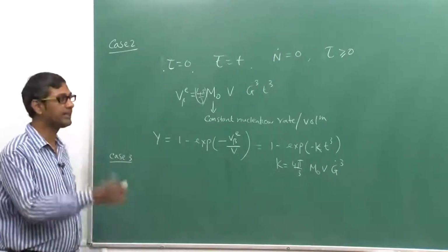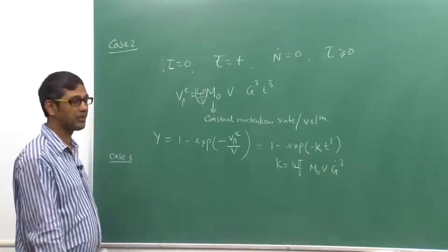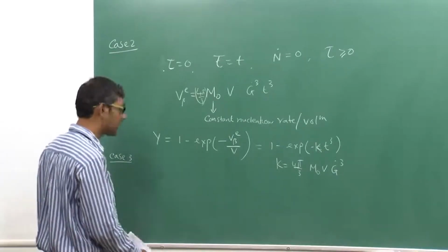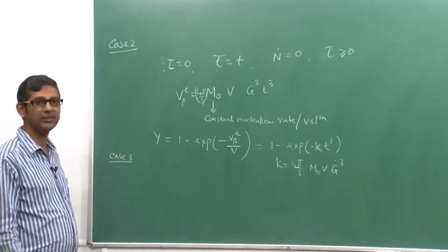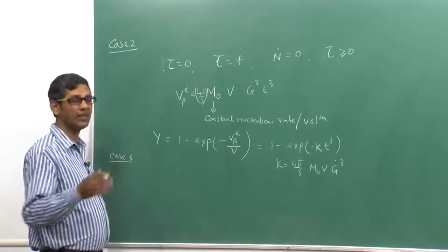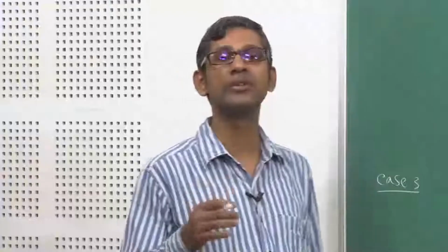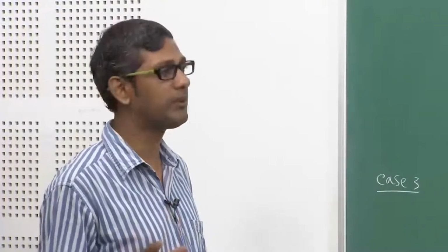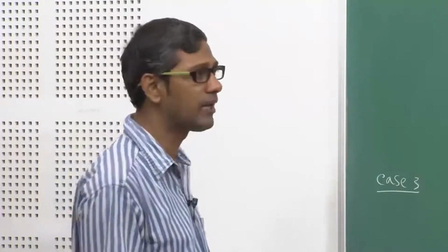Suppose you have very small fine grained crystals. That means you have a large number of grain boundaries, because of the fine grains the boundary area is large, and nucleation always happens at grain boundaries, we know that, or grain edges or grain corners or the triple points. These are the places where heterogeneous nucleation happens. So nucleation will take place randomly. If the grain boundary characteristics are random, that means the grain boundaries are not special type, not sigma 3 type grain boundaries, they are basically random grain boundaries. In those cases nucleation will also happen randomly along the grain boundaries.